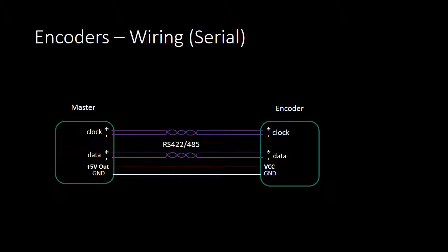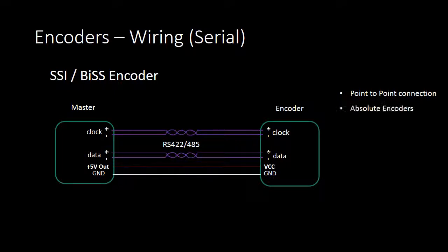An alternative to parallel communications is serial. There are several standard serial buses available, as well as the standard industrial networks. SSI encoders offer an all-digital point-to-point serial arrangement with speeds up to 1.5 MHz. BISS is a similar open-source serial communication used with absolute encoders. Typically, this arrangement has 2 wires for power, 2 for clock, and 2 wires for data.